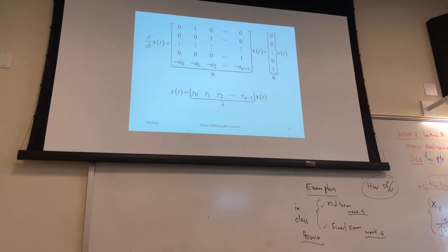I don't want you to confuse this one with the modal controllability matrix. In that case, you have to talk about a Jordan block, the block diagonal case, and then you check which B is non-zero. We have learned that kind of thing before. If it's all diagonal, then you check the B, and if B is not zero, then it's controllable. But in this case, it's a canonical form, the controllable canonical realization. In other words, you just have cascaded integrators. Remember, cascaded integrators.